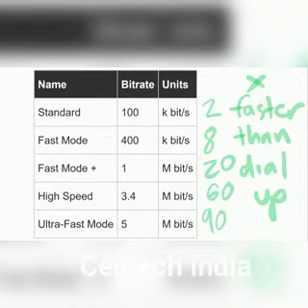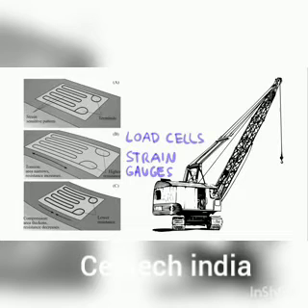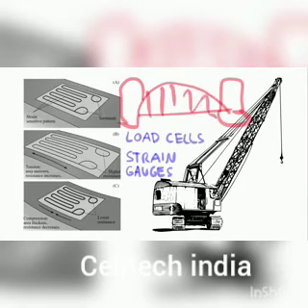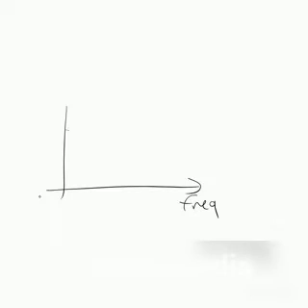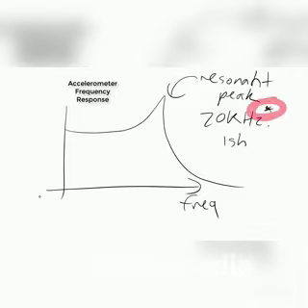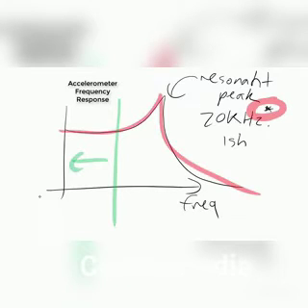I2C until recently only had 4 speed grades, but in 2012 a 5th one was introduced. These speed grades might not be good enough for things like internet or displays, but they are ample for most sensors and data acquisition applications. The sample rate of common sensors, especially mechanical ones, is mostly quite slow. Strain gauges, which are on bridges, only require a few hertz for the sample rate. Even accelerometers rarely go above tens of kilohertz, and the I2C bus in the megabit range easily accommodates the data